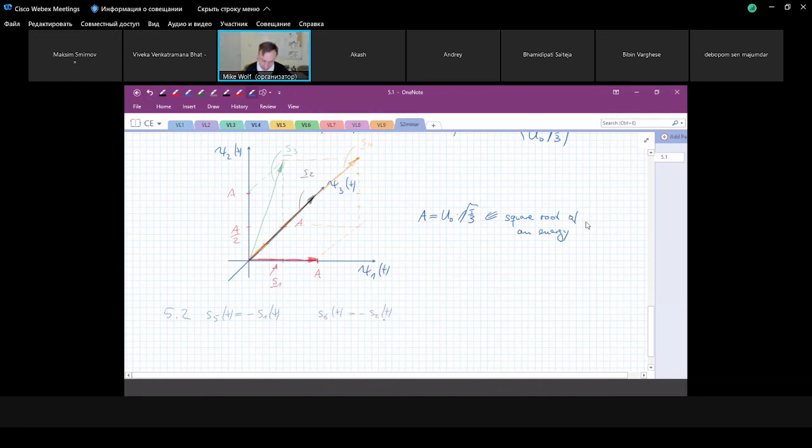So we know the signal vectors need to be antipolar, yeah, because we have this notation here of the signals. S7, so we have 8 signals, and this is minus S3 of t, and the 8th signal is just minus S4 of t. So once we found the signal vectors for S1, S2, S3, and S4, we also have the signal vectors for S5, 6, 7, and 8. And the signals are given as this.